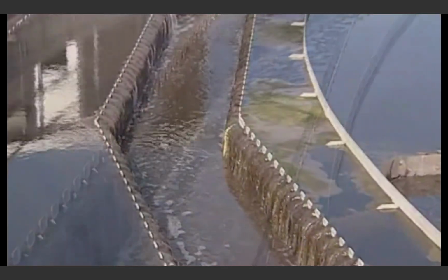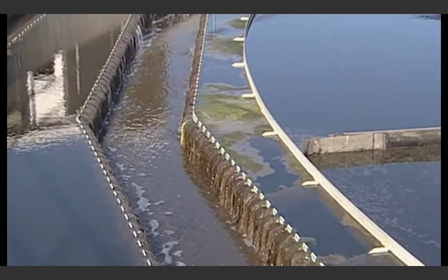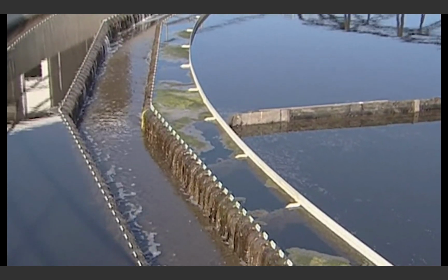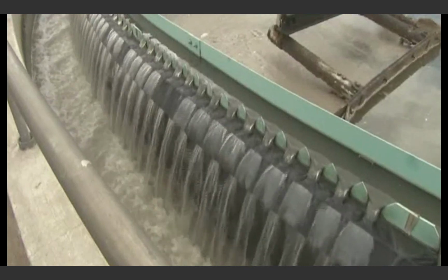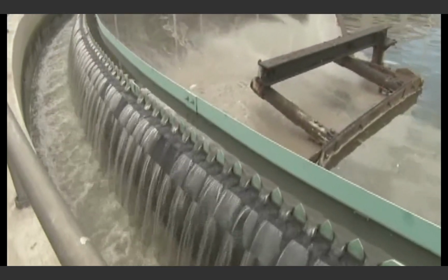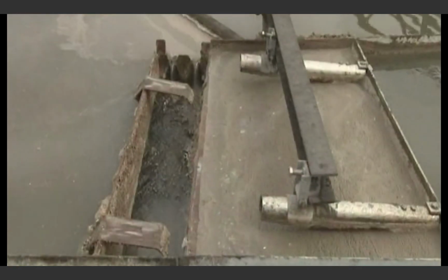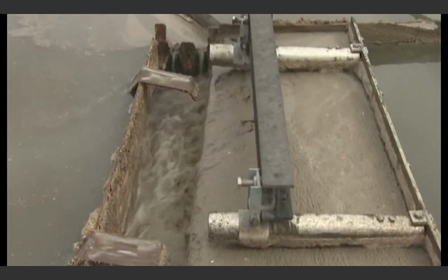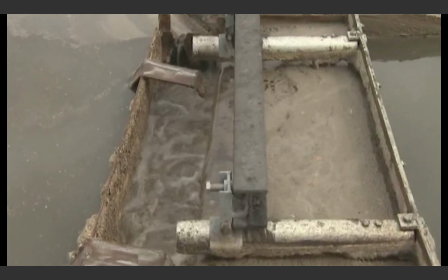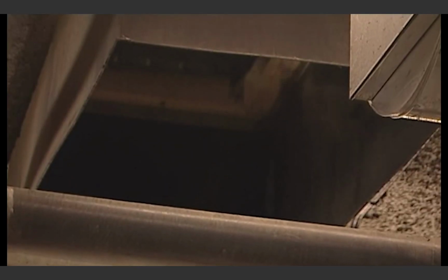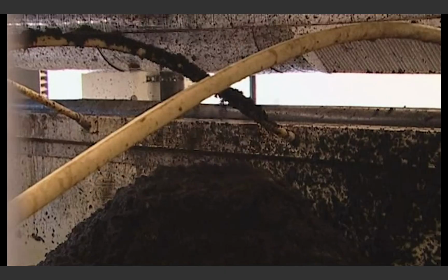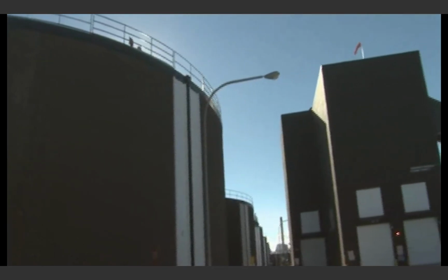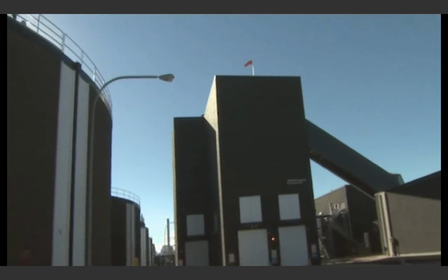The goal is to remove the majority of total solids from the water, even if that means multiple clarifiers or recycling the water back through the clarifier more than once. Once that is accomplished, liquids flow one path and the sludge another. Sludge can be removed at intervals or continually removed by mechanical scrapers installed to scrape the sludge away. The solids removed from the bottom of the clarifier or sedimentation tank are called primary solids. These solids are further handled at the plant through dissolved air flotation, digestion, and disposal.